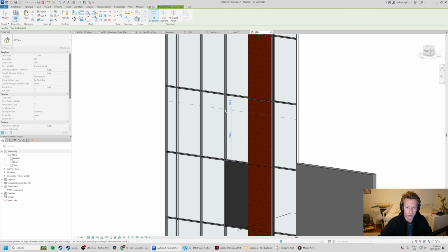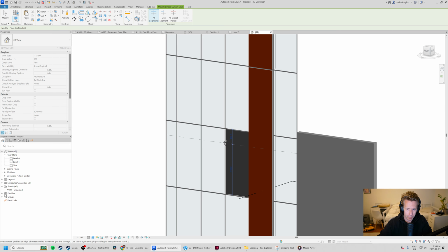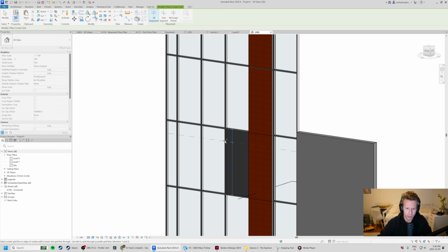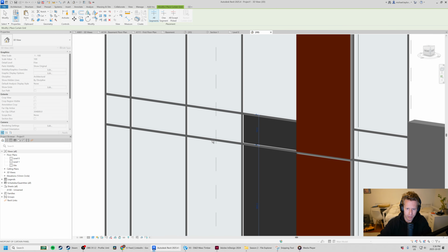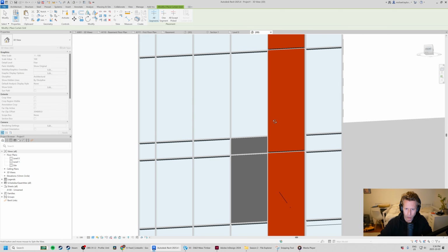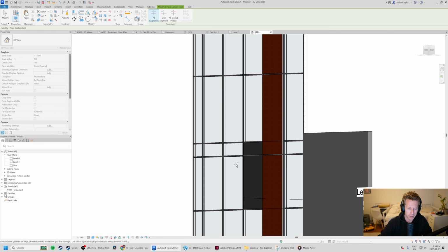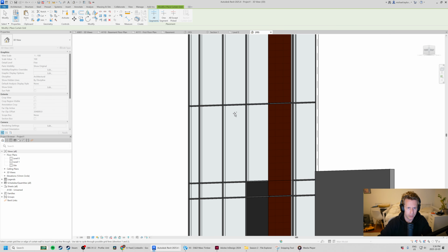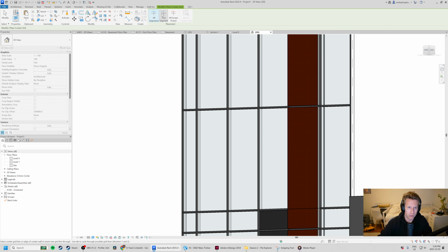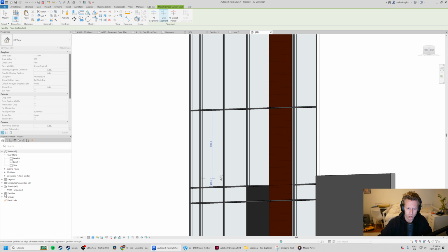where could I insert another line, a horizontal datum within my curtain wall grid that might be helpful for something like a spandrel panel. So if I go ahead and click here, you should see a brand new line with all of our mullions already drawn in, because that's what our family is currently showing. So we can also choose one segment. So if I come in here, I can just choose one piece.